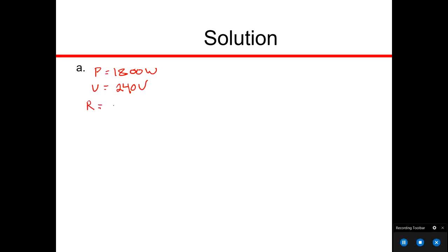So we saw that the wire had a resistance of 1.0 times 10 to the negative 5 ohms per meter, and that it's being sent over 300 kilometers, or 3 times 10 to the 5 meters. By multiplying this, we can get the total resistance that our current has to travel through, which is 3 ohms. Now, if you think wires are quite thick, so 3 ohms, reasonable resistance. So then we can start our calculation.